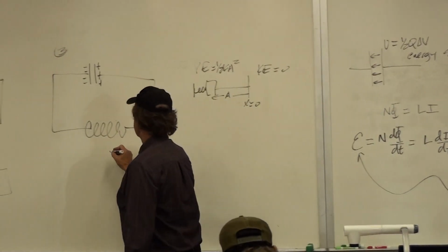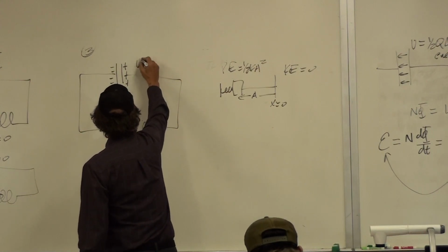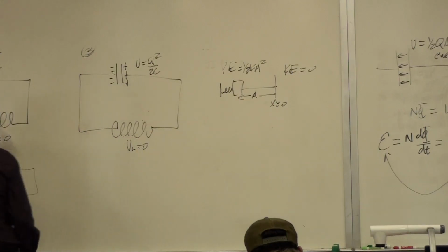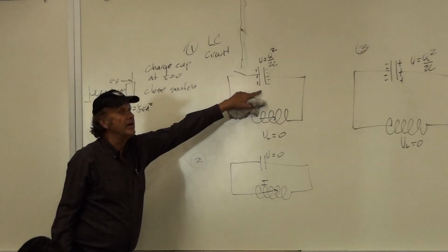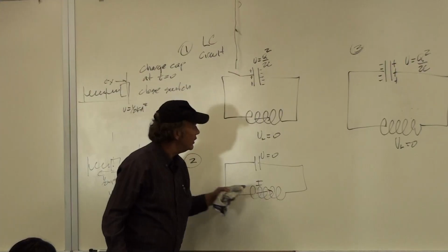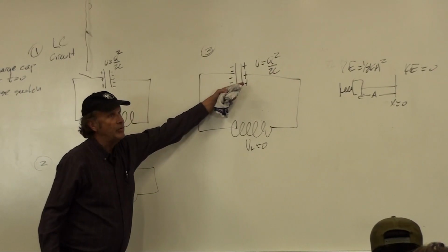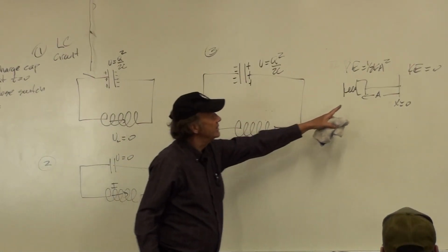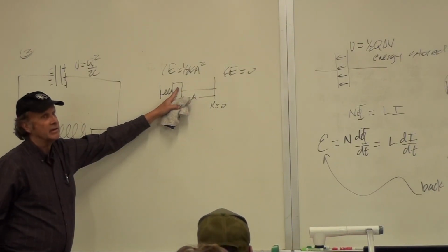So here, we've got the energy across the inductor is 0. What we have here, the energy across the capacitor is still q squared over 2c, but it has an opposite polarity, notice, to what we have over here. So it's completely charged, but on the other side, because all that inertia drove that current through. The changes in flux kept it going until finally there's no current, but at that point the capacitor now is fully charged, but with the opposite polarity. So that's analogous here to the mass moving in the opposite direction and creating a compressed spring.